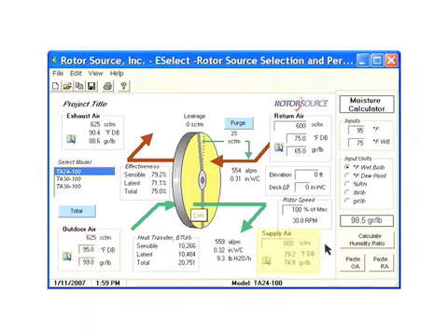The energy recovery program features a rough schematic of the wheel and works using parameters for outdoor air, the air which will be supplied to the space, the air which is returned from the space, and the air which will be exhausted as spent exhaust. The program also includes a model selection, which is considered against our drawings, price, schedule, and other aspects.